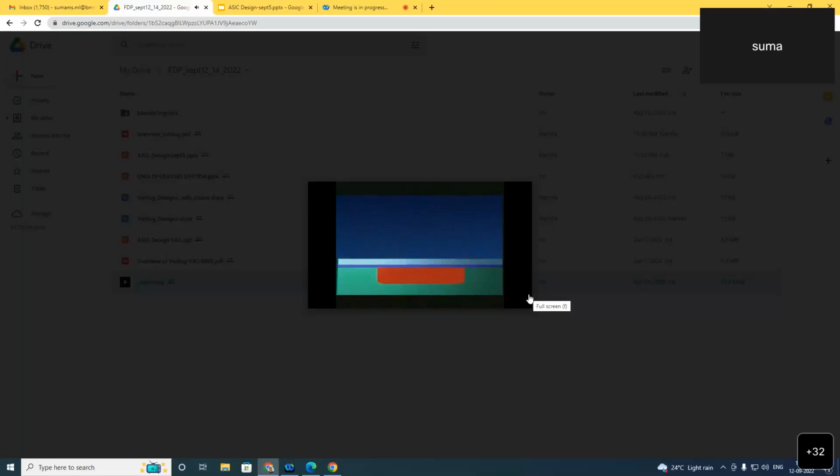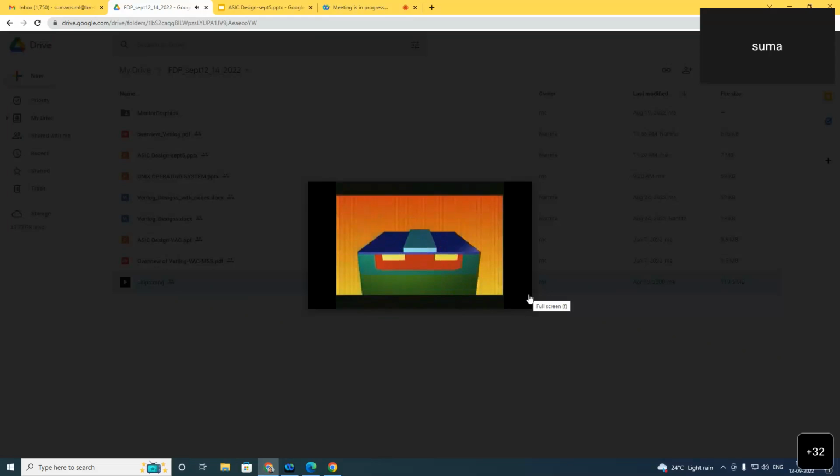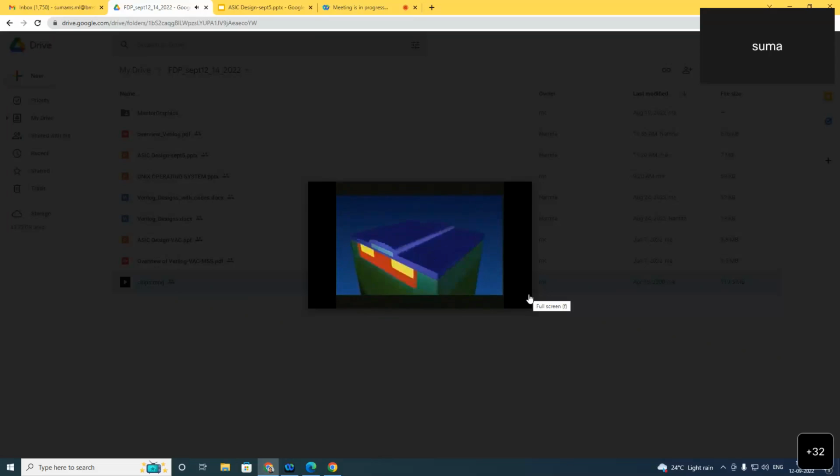And once again, a layer of lacquer is applied, exposed, and developed. The silicon which is uncovered by this process is then etched away. Another series of treatments involving lacquering, exposure, treatment with atoms which penetrate the silicon, more oxide layers, etc., is performed until the whole pattern is complete in all its layers. Some 300 to 400 process steps are required, along with 15 to 20 different masks with microscopically small patterns.